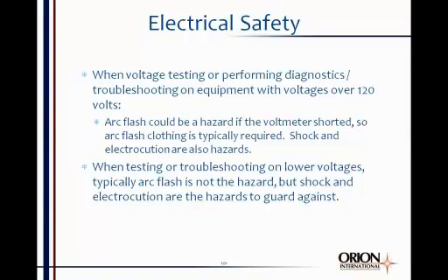So here are a few of them that you need to be aware of if you're going to do voltage testing or you're going to do troubleshooting on equipment and there are voltages over 120 volts. You need to be aware that arc flash could be a hazard if the voltmeter were to short. And what I mean is, what do you do with the voltmeter? You take that meter and you place it phase to phase. You place it phase to ground. You're testing, performing diagnostics. Maybe testing as part of lockout tagout for lack of voltage.